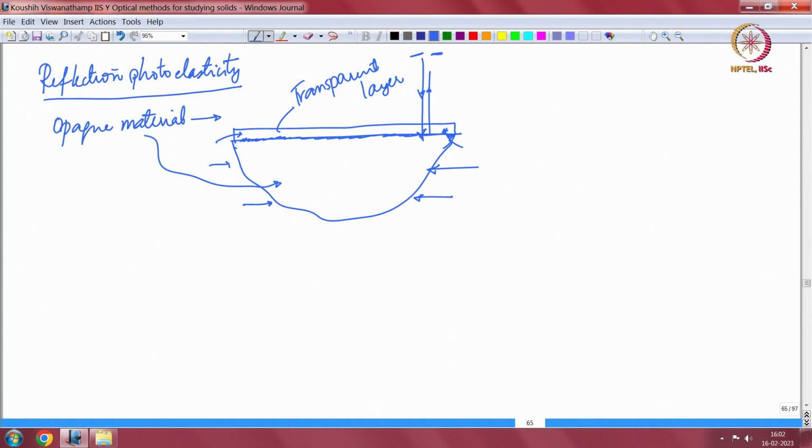Now, obviously you can't have this beam exactly perpendicular, because if you did then the polarizer and the analyzer will coincide. So, there is usually a very mild small angle that is given. So, you actually need a fair distance from the imaging system to the surface. You will often see people use high zoom lenses for reflection photoelasticity, and this small deviation gets amplified over a longer distance.